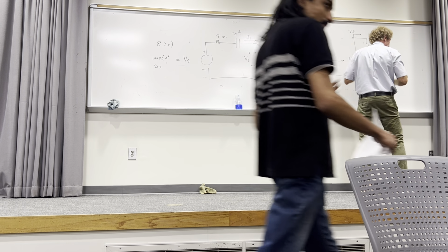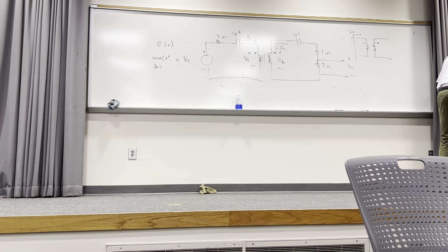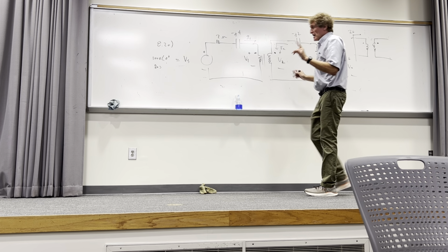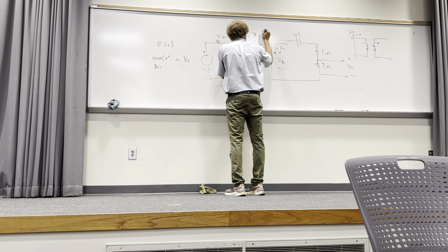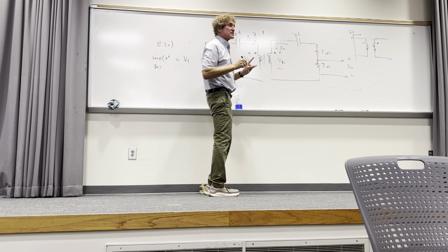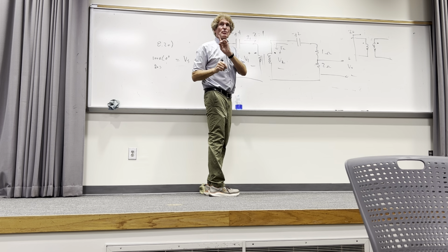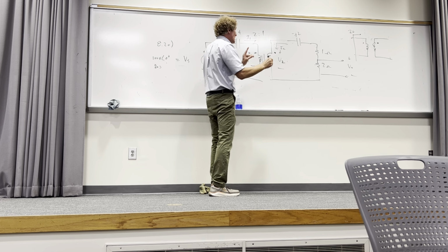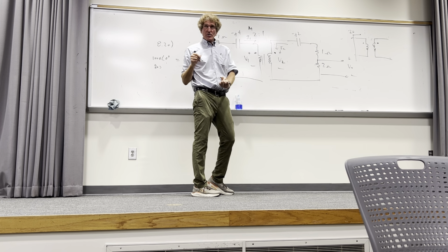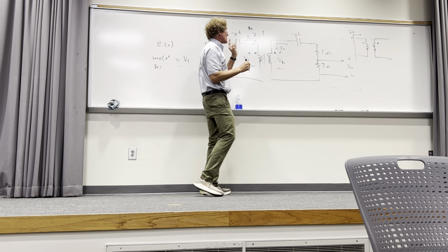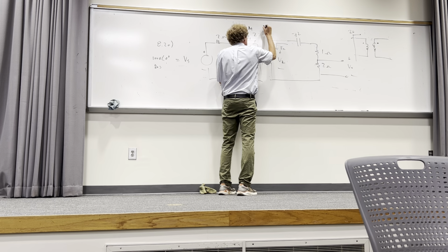And then the turns ratio on this one is 2 to 1. This is important. So it says for every 2 turns on the primary side, I have 1 turn on the secondary. Label this in your notes. Put an N1 or the number of turns on the primary side there and N2 here.